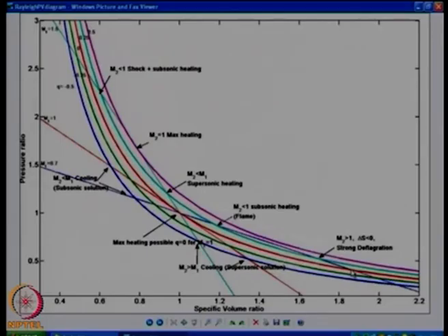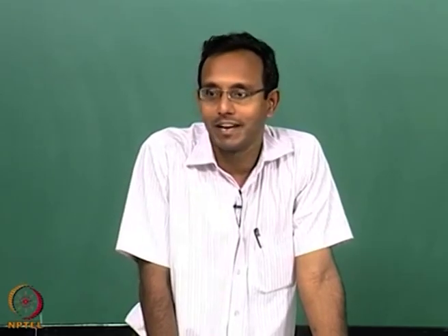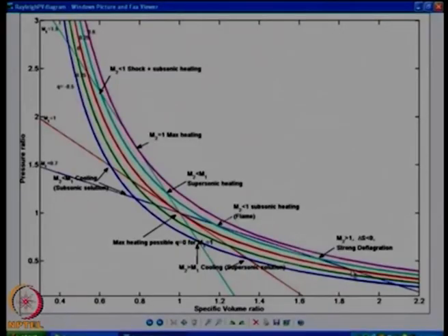Okay? And in our flow where P equal to rho r T is our gas law, it is not going to be valid. For us, our delta S will be negative, that is that particular situation, and so that particular solution of the subsonic Rayleigh line cutting with this red curve for Q equal to 0 is not possible for us. Okay? That is one thing. And on the supersonic side, it does not go at all. Okay? That is on the other side, it does not go at all, there is only one possibility, it says, for Q equal to 0.